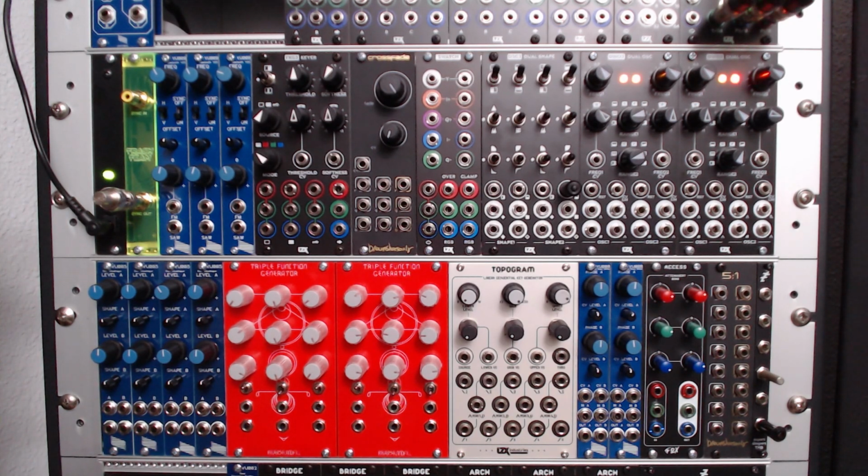Well, the purpose here is I want to process 2 independent RGB signals. Those are going to be coming out of TBC2, and that's what this gap in the rack is here. So when TBC2 arrives, I'm going to be able to take 2 RGB signals and process them through VU005. And that's going to take up 3 modules because each module has 2 independent channels. I've also got a 4th module left over, so I can also process maybe a luminance or Y signal, or maybe an animation low frequency signal, or some combination of those. So in my case, 4 modules is not overkill. That's actually the magic number. Let's take a closer look.